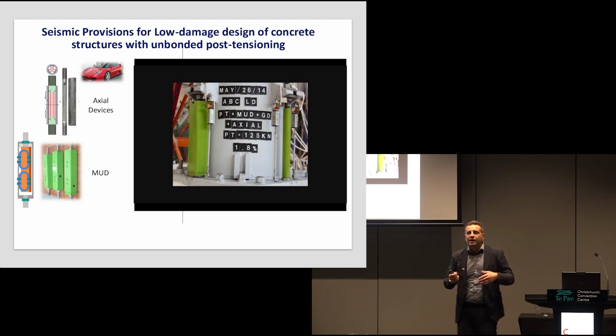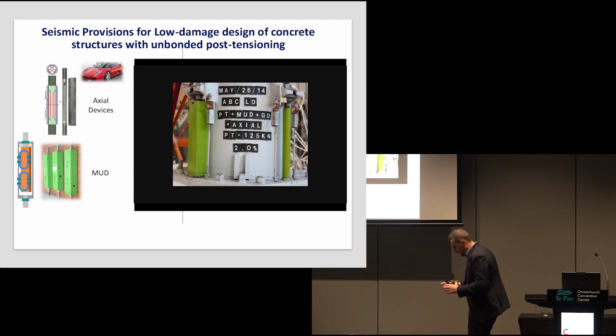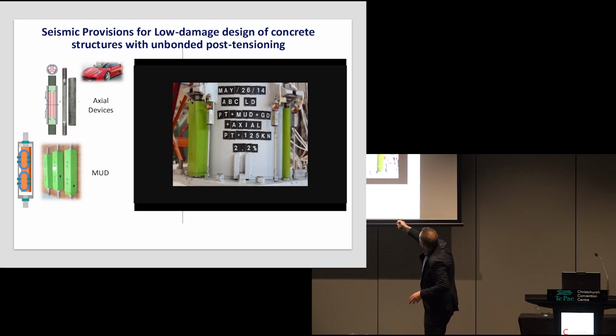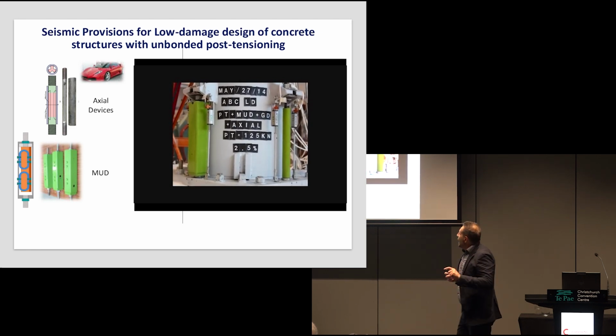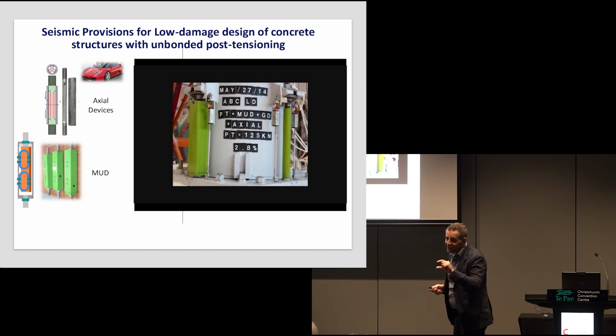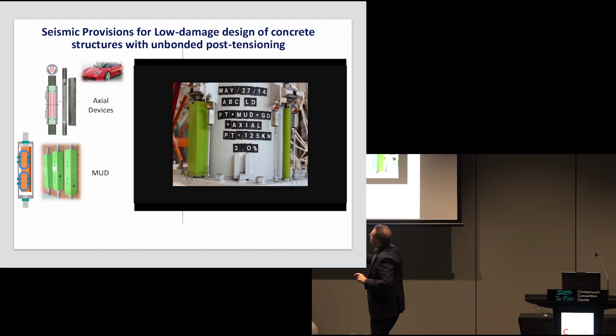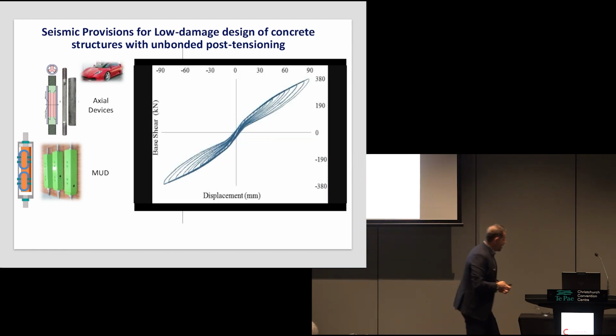Right now we have armoring of the bottom part. We use the dissipative fuses, which are external. We have different ways of preventing shear failure with mechanical shear hinging, and we have traditional axial devices, or we have U-flexural plate.